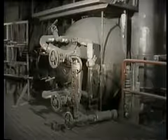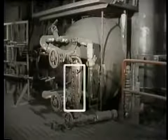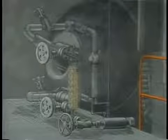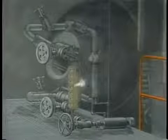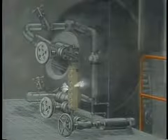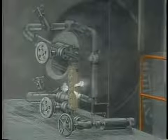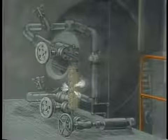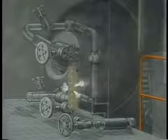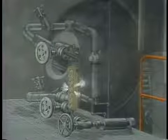For example, most boiler drums have gauge glasses like this that can be used to check the water level in the drum. Due to the tremendous pressures and temperatures that a gauge glass is subjected to, leaks may develop. In most cases, the amount of water that leaks out of a gauge glass does not affect the operation of the boiler. The operator may choose to live with the leak until the boiler is taken offline for scheduled maintenance, or the operator may isolate the gauge glass by closing shutoff valves on either side of it. Once isolated, maintenance can be performed on the gauge glass while the boiler continues to operate.